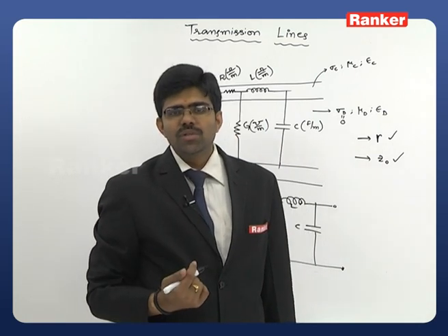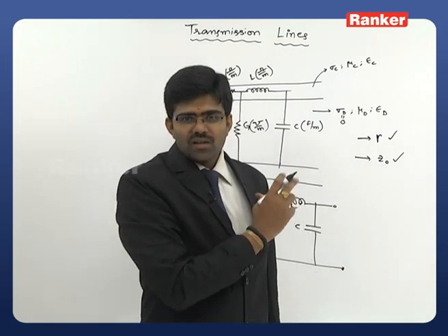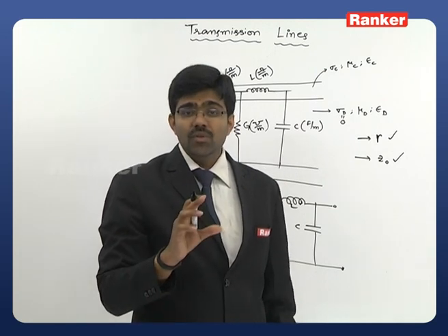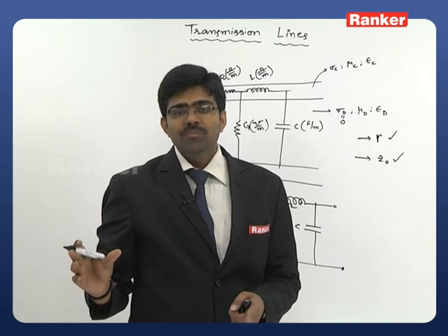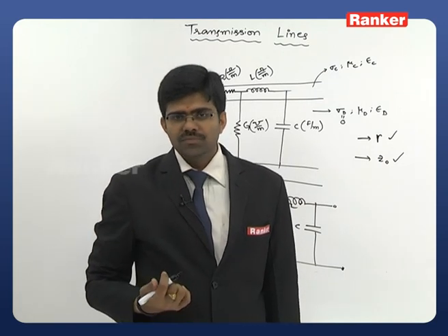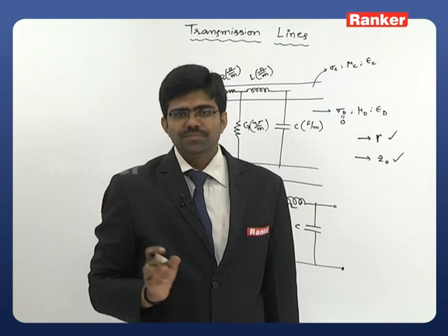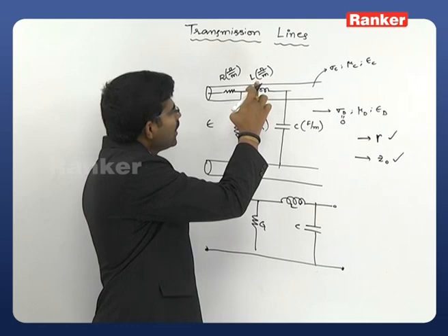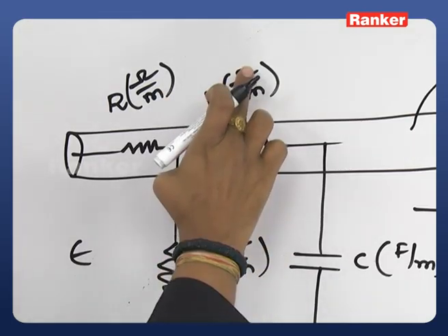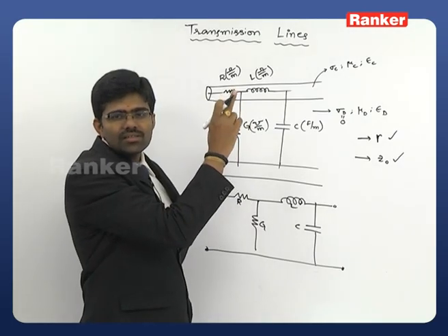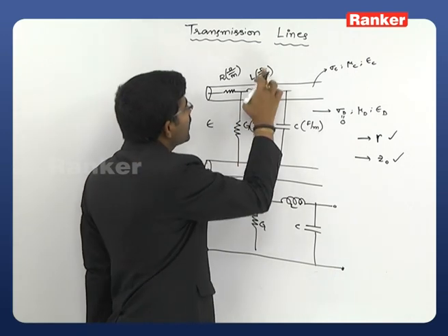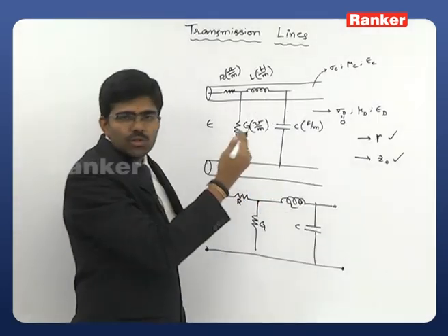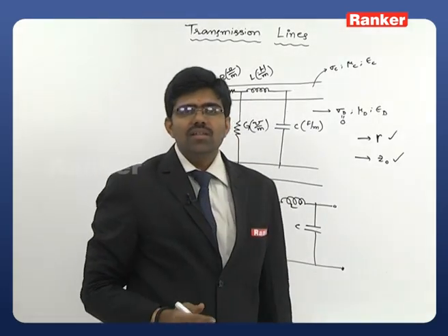Now in this session we will try to analyze the transmission line, and get the wave equations for it. From those wave equations, or the equations of this transmission line, we will try to get the secondary constants also, that is gamma and Z0. Just observe the structure of our transmission line. Here resistance is ohm per meter, inductance is not ohm per meter, this is Henry per meter. The unit of inductance, which is distributed over our entire transmission line, is Henry per meter. Please ignore the previous one; we are supposed to take inductance as Henry per meter.